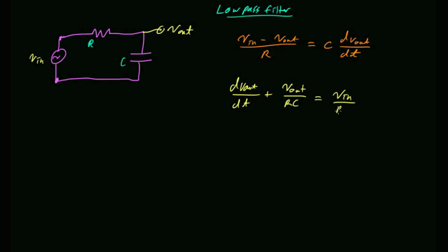Okay. So that's always a differential equation. In circuits 1 and 2, basically what you learned was how to solve this differential equation for different kinds of inputs. The approach that they typically teach you is, let's start with certain kinds of inputs and solve the circuit for those special cases. And then hope maybe we can come up with something useful. But this differential equation is always true, regardless of what your input signal is. Your input signal could be a cosine, a step input, a speech signal, a brain signal. Whatever signal V in is, this differential equation will always correctly predict the output if you can solve it for V out. That's the tricky part, solving it for V out.